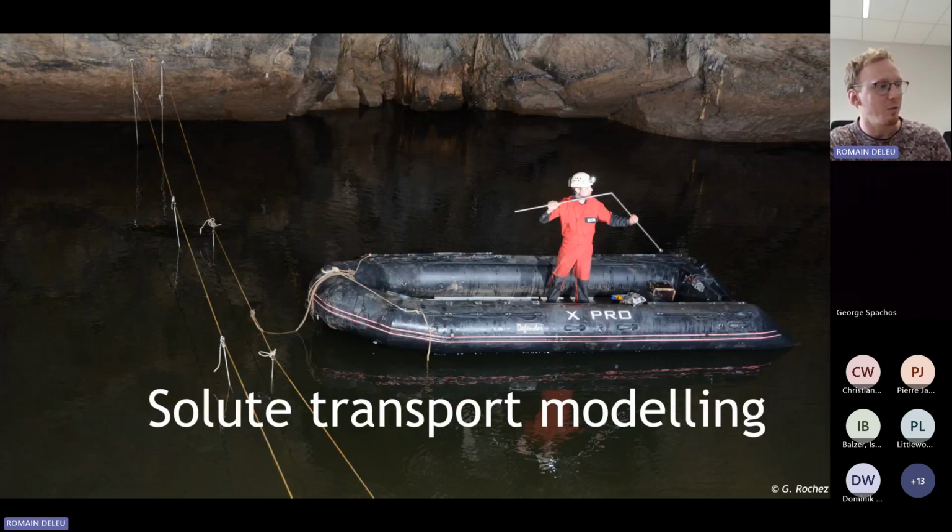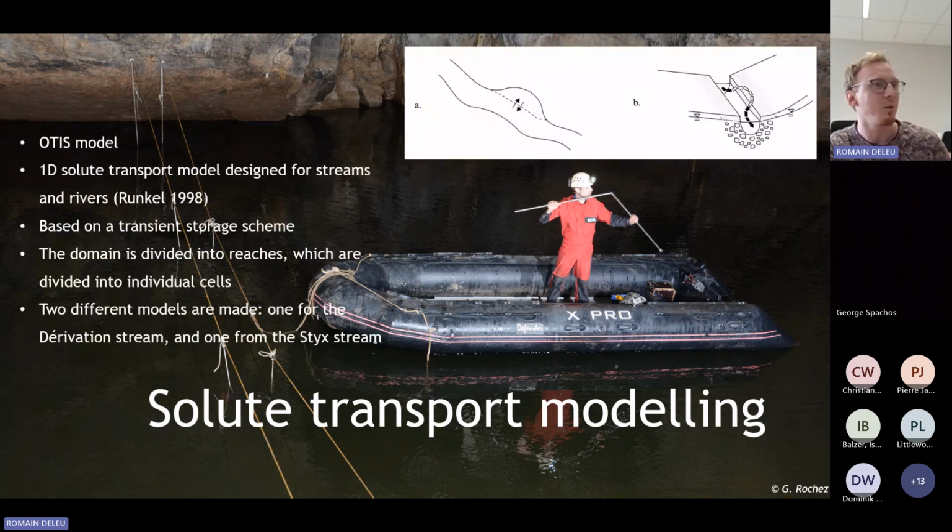We also did some solute transport modeling in this system. So we use the Otis model, which is a 1D solute transport model designed for streams and rivers, which is based on a transient storage scheme. As the figure shows, the model considers a small storage zone along the stream, such as a side pool or the river sediments, that can hold the tracer for some time.